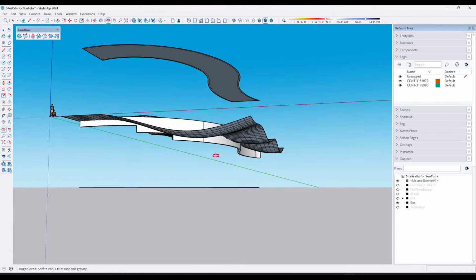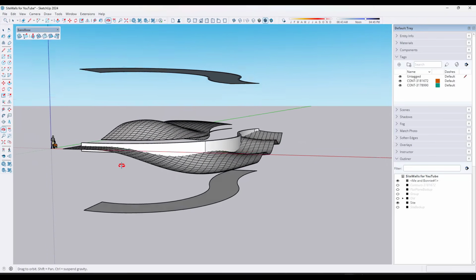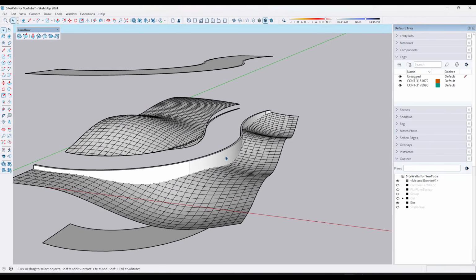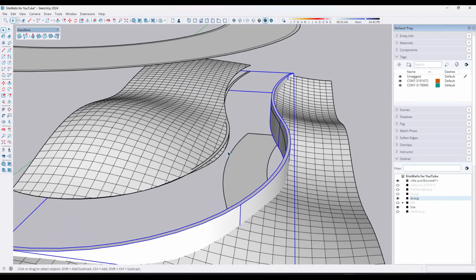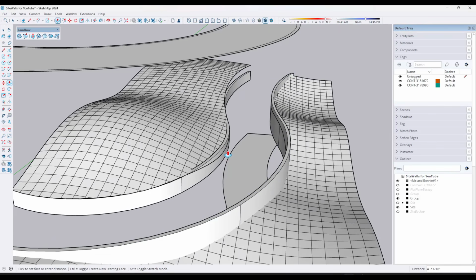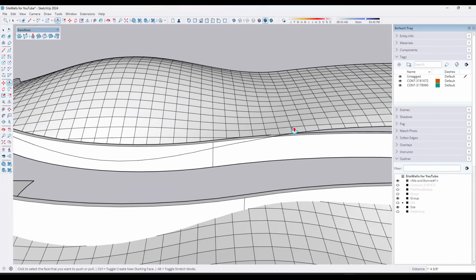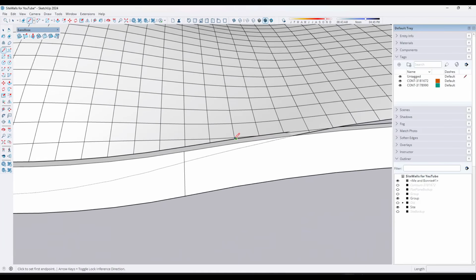But if you did want to be a little bit more detailed, you could just use the push pull tool there. But you've got one wall right here, and I'm going to go ahead and triple click on it and make it a group. And then I've got my other wall over here. And again, I'm just going to push pull this down so that we're through. We'll push pull it up like this. And again, probably what I'm going to do is find the places where I need to split this wall out.